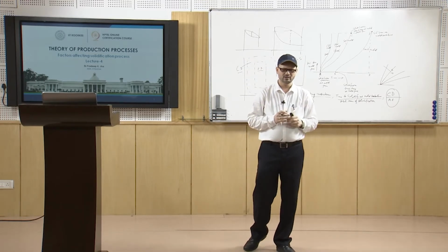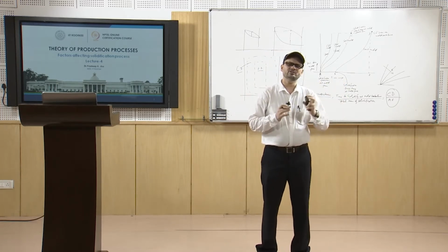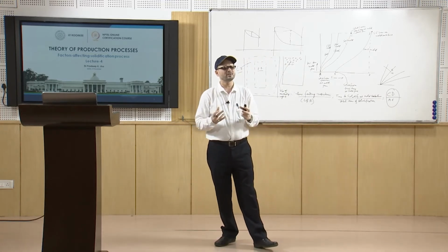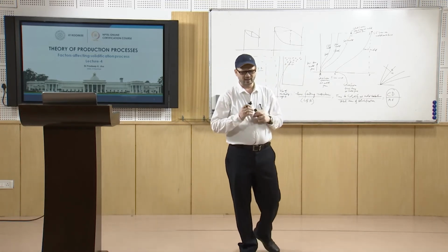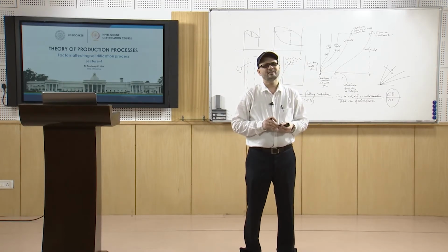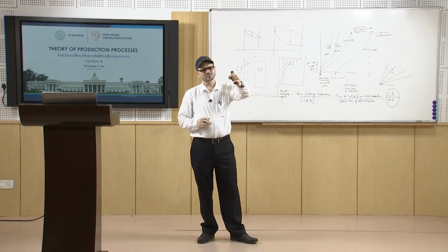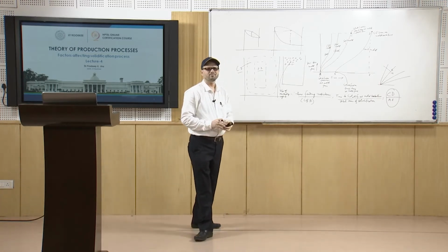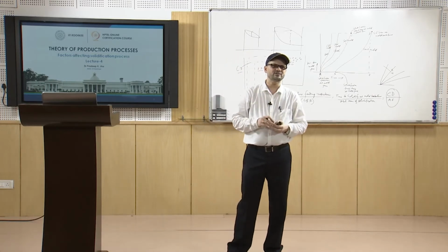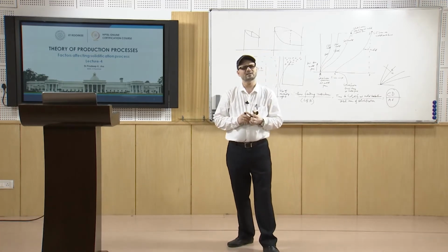dendritic structures are not that desirable, because you have the dendritic arms, and as we discussed, you have the chances of liquid metal getting entrapped in between the dendritic arms, and that will be a source of casting defects. Now, in the case of commercial alloys, this is the normal typical structure, where you will have the columnar dendritic grains near the surface, and then you will have equiaxed dendritic grains near the center of the casting.